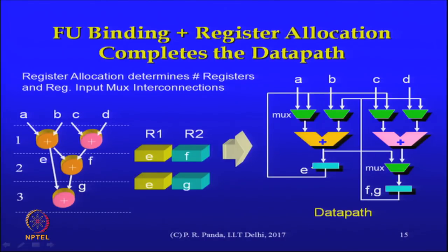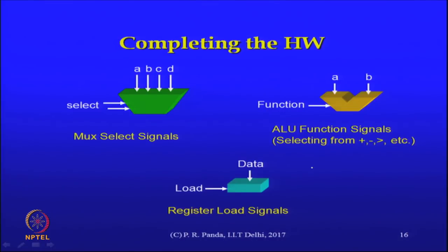Our FSM was not quite complete. We had the states, we had their transitions, and we did have an idea about the conditions. As of now, those are simple don't care conditions, but for the outputs I actually need to provide the right select signals into the muxes. So, there are a few other things to complete the hardware. The mux select signals need to be decided, which resource should be connected to which input of the mux. The order is important, right. So, those I need to decide, and correspondingly I need to fill in the details on the FSM action table.